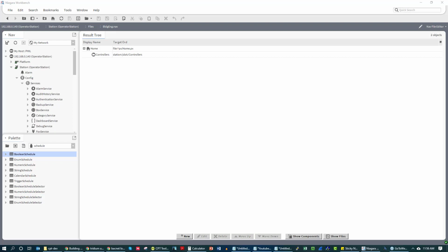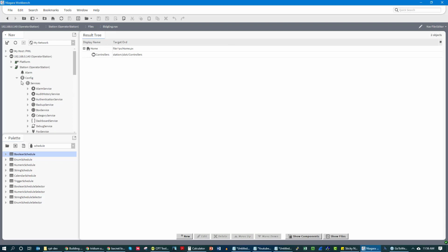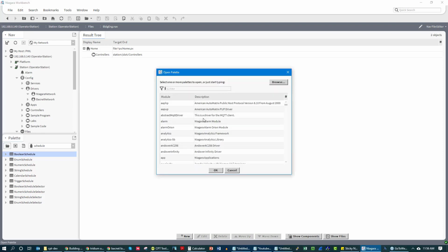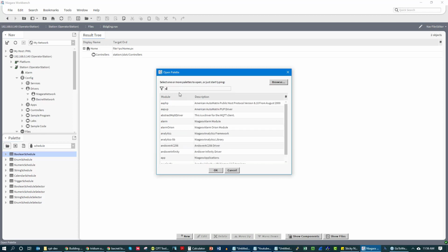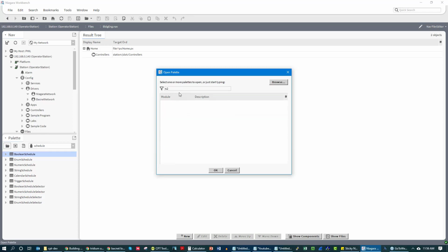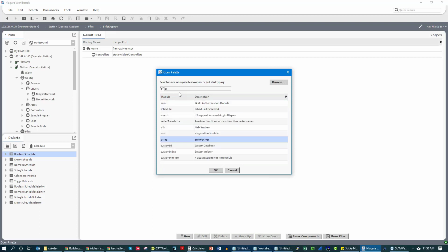What system does Siemens use for their controllers? Like their legacy or their current? Their current ones, I believe, are BACnet IP. So Niagara uses, let me show you. Niagara uses the Niagara network and Fox protocol to communicate between Niagara devices. But it also has BACnet, Modbus, it has a ton of stuff, right? Andover, I think that's N2, but I thought SNMP,